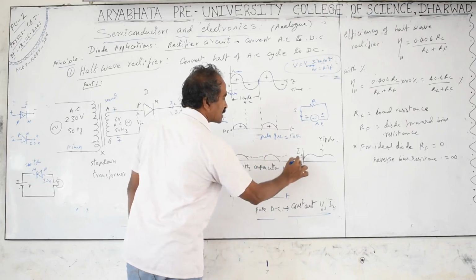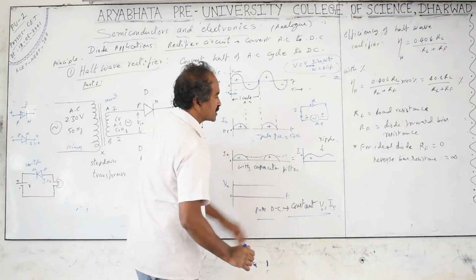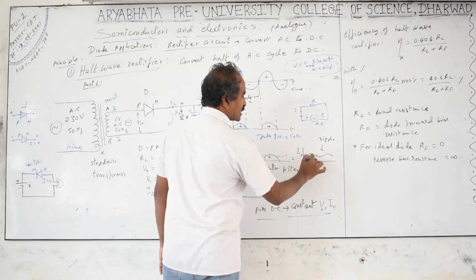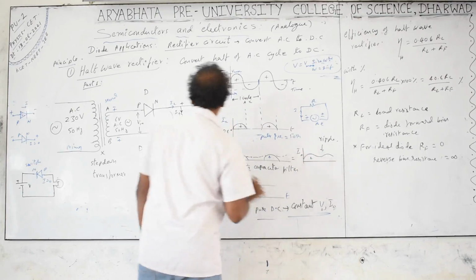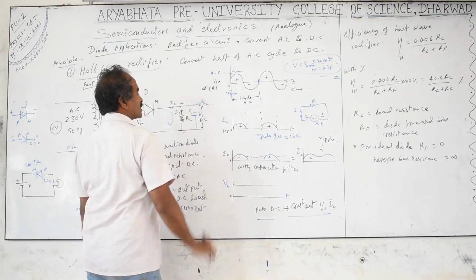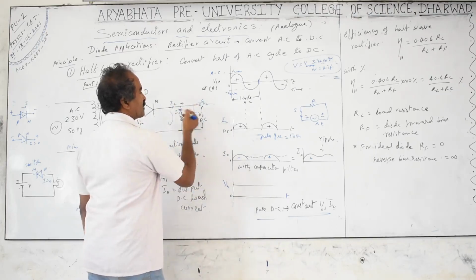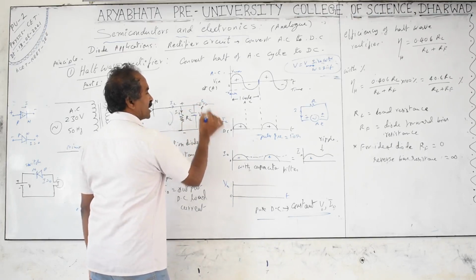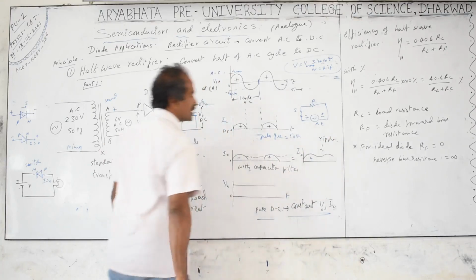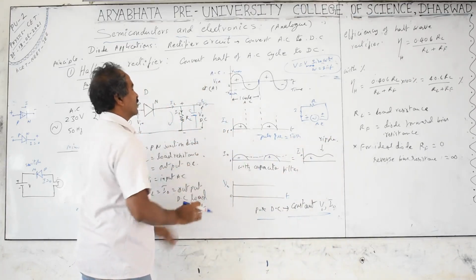The result is like this. It is only positive. You have only positive voltages, no negative voltages. It is a DC, but not pure DC, you can take it as near DC. In this case, with the help of capacitors, or even inductors. Inductors must be used in series and the capacitor in parallel. The inductor opposes the change of current by inducing a back EMF. So the inductor also reduces these ripples. Small waves are called ripples, but only positive ripples. Voltage slightly increases and decreases, but does not become reversed.